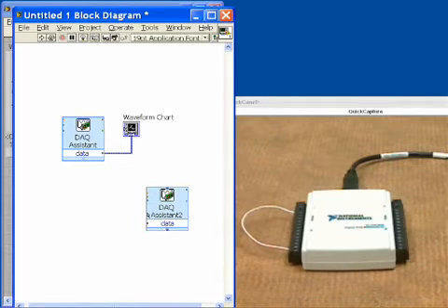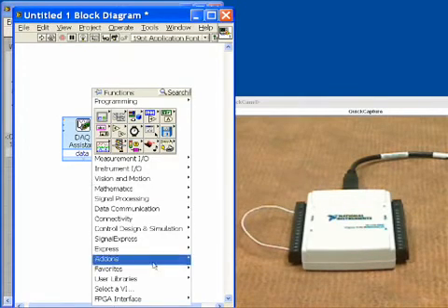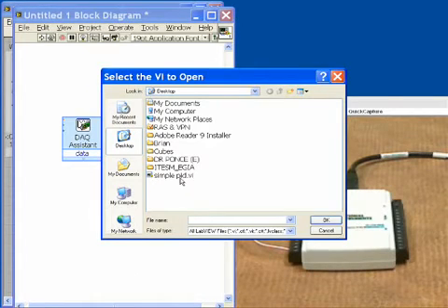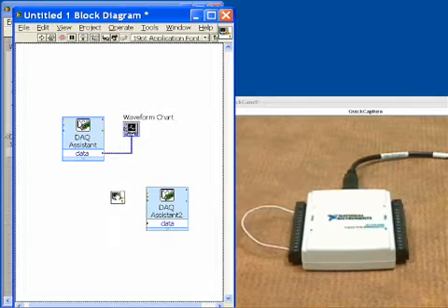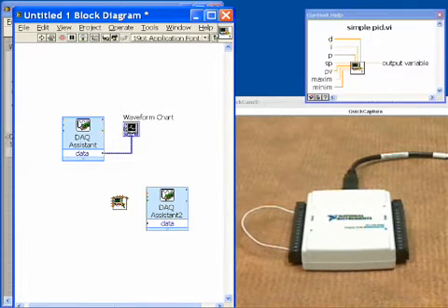Now we need to choose our control algorithm, and we'll select a simple PID algorithm, and we'll get this by clicking the right mouse button again, and we'll go down to Select a VI. Now PID is an algorithm that does control, and you can find out a lot of information on this at www.ni.com. We actually have a toolkit that makes this very comprehensive, and this is just a simple user-created PID algorithm that I'm using here. What we're going to do is, you can see from the help window that's come up that I have a bunch of parameters that I need to set for this.